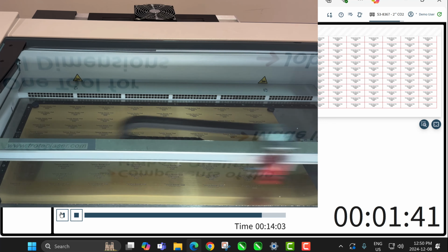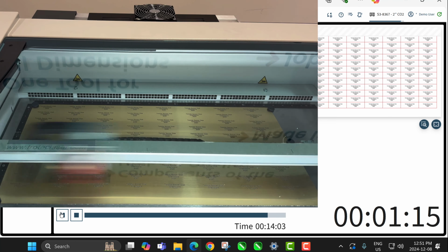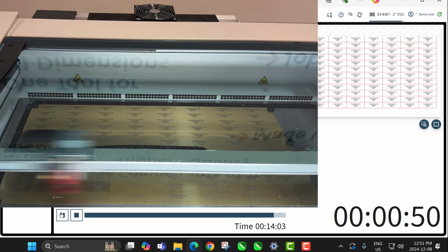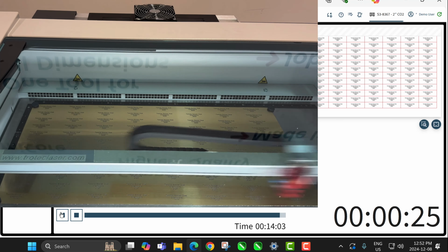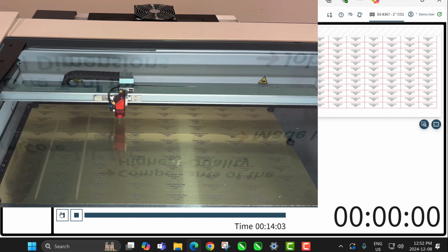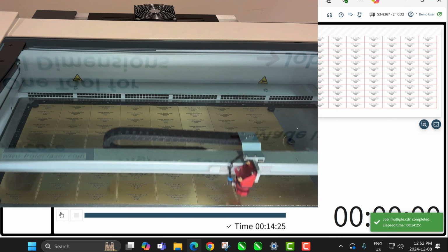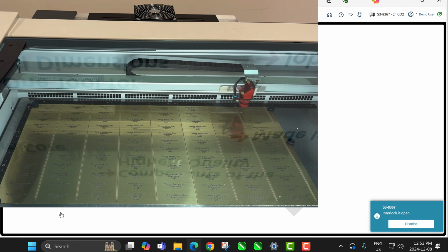Again, if you have somebody that's very good at it, maybe you'll get a stainless steel piece cut exactly the size of the table that you're working with, in this case 17 by 29, but whatever. Again, I just like using the magnets. You'll notice that I'm outside of the engraving area when I'm engraving here. So just remember that when you put the magnets on there, you've got to account for this in the software setup.